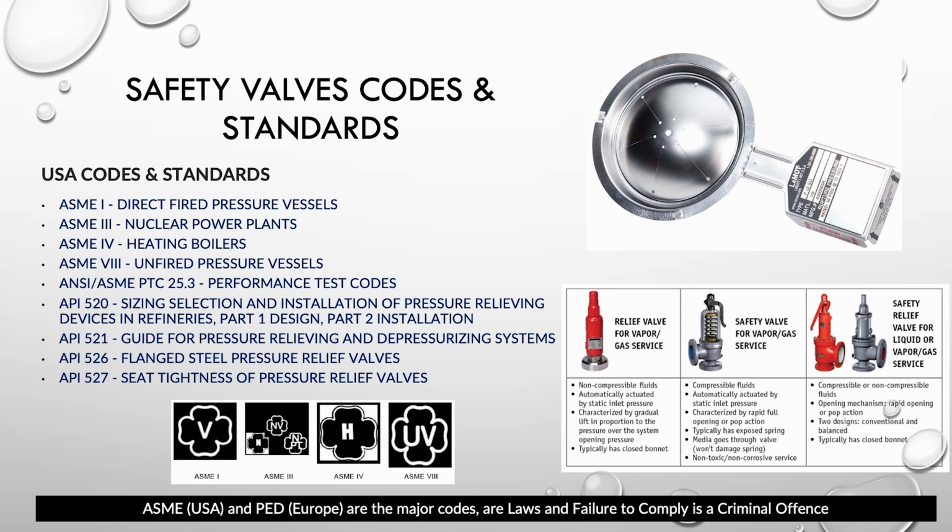In the beginning, you'd find people struggling with that concept, the pressure relief valves, or even a rupture disk. They are literally valves. They just have more regulations around them because they are dealing with safety and hazard. Because at the end of the day, the pressure relief valve is going to need to protect equipment, protect the environment, and protect the human beings around the plant. So the fact that pressure relief valves deal with health, safety, and environment is what makes it super unique and has a lot of regulations around it.